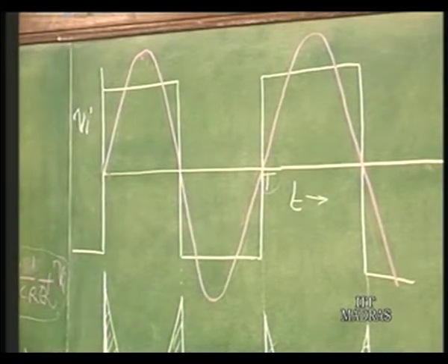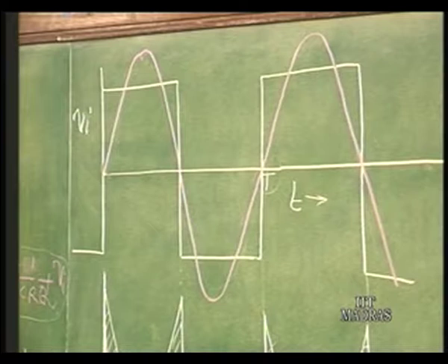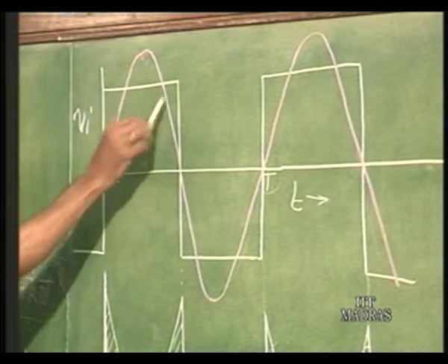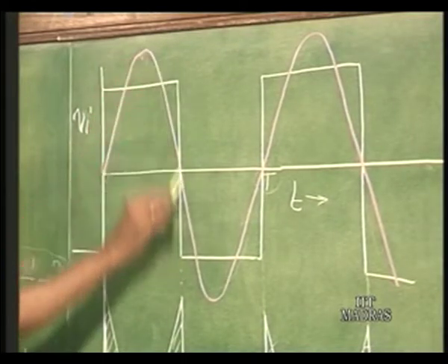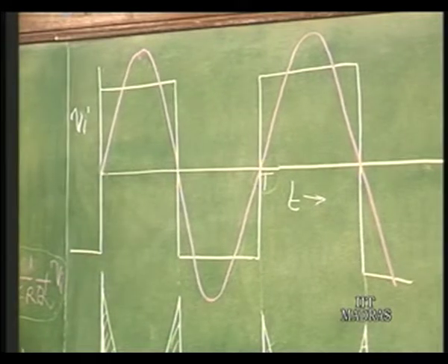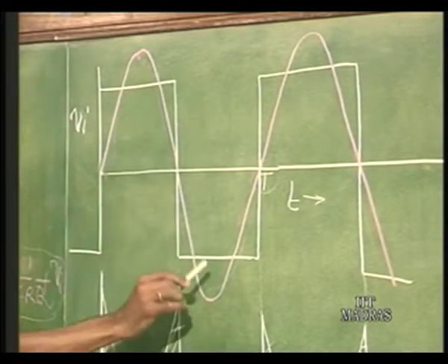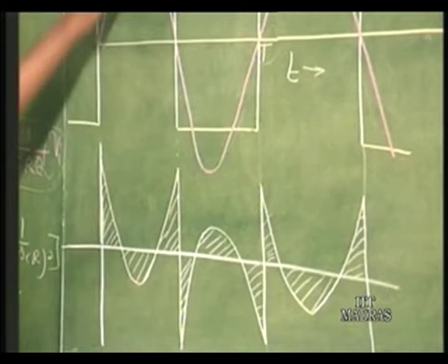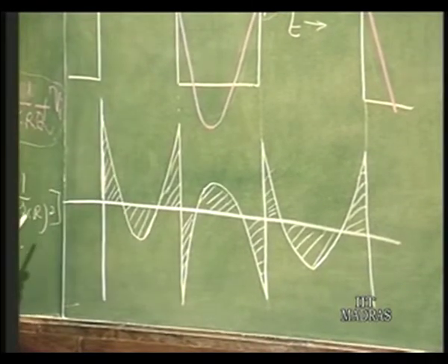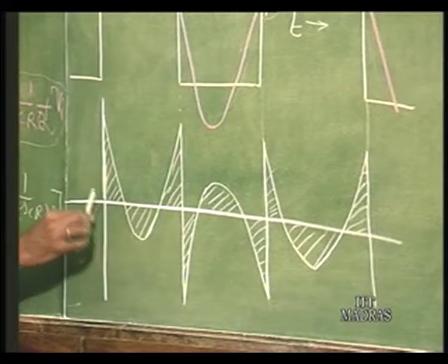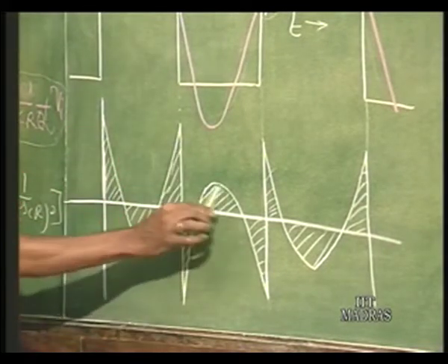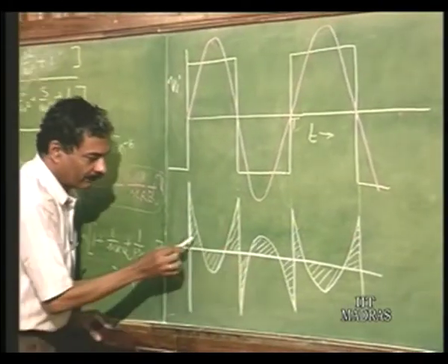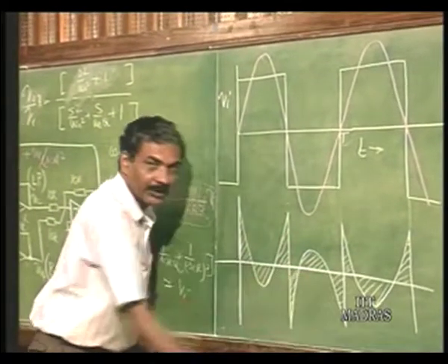And it will be almost Q times the input. So, the fundamental amplitude will be very huge. If I apply some value of input signal, Q times that is going to be the fundamental output, compared to the fundamental of the input square wave. Now, if I see the notch output or band elimination output, this fundamental is going to be eliminated from that if it is exactly tuned to omega naught, and you will see that from the square wave I am removing the fundamental. If you remove this fundamental, you are subtracting and you will get a waveform which contains only third harmonics and higher harmonics.